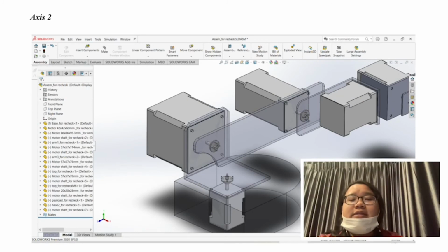For motor 2 in axis 2, it is inappropriate for this design. The motor 2 has 7.2 Nm. That's enough for the required torque of 6.3906 Nm, but has an inappropriate size because it's bigger than the design. In this case, to develop the design, we can use the timing belt to apply the torque and decrease the size of the motor.